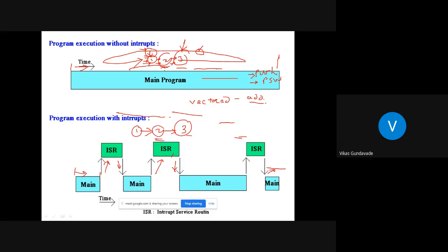Now we will take the same status. If suppose the microcontroller is executing the second task and the event has occurred in task 1. Here, if any event has occurred, and that event is triggered or that signal is provided by the interrupt, then what will the microcontroller do? The microcontroller will stop its operation here. It will shift to the event, serve the ISR, and after serving the ISR, again return back to the second task, and after the second task it will execute the third task.